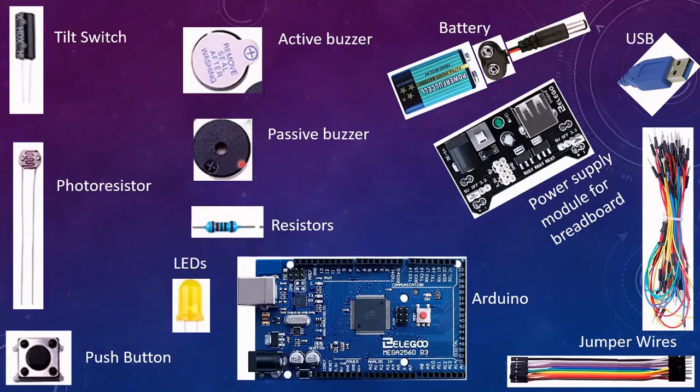If you just go from having no current flow through it to, say, connecting a battery, it will just make a click once. And so to make this into a buzzer, you need to send pulses of electricity through. So on, off, it'll go click, click, click, click, click really fast. And eventually, if you can make it click fast enough, it will sound like a buzz. So there's kind of a difference. This one will just buzz if you give it a solid current. This one you have to send a special pulsed signal to. We're probably going to use just the active buzzer today.